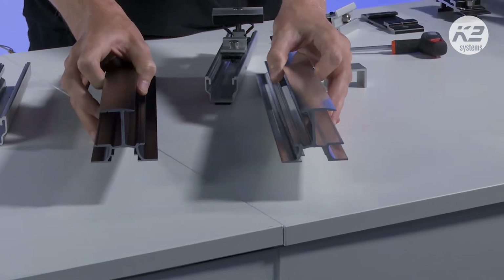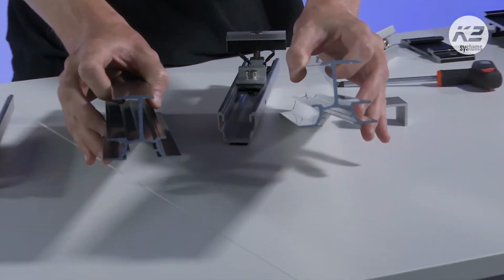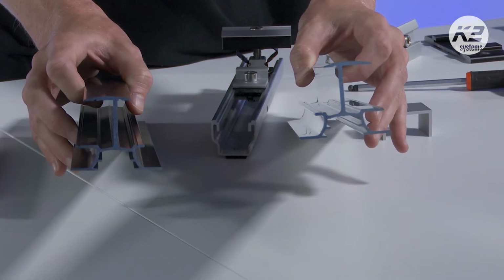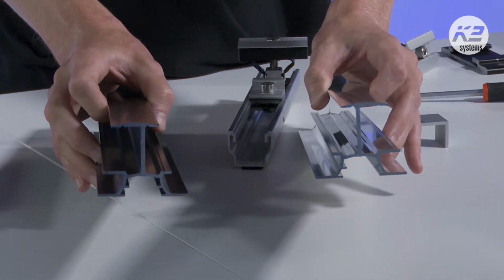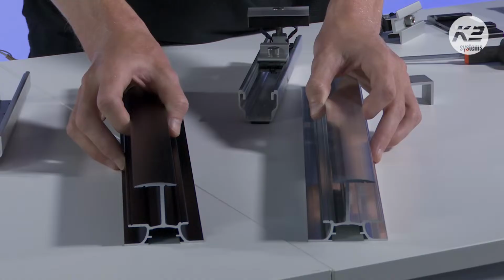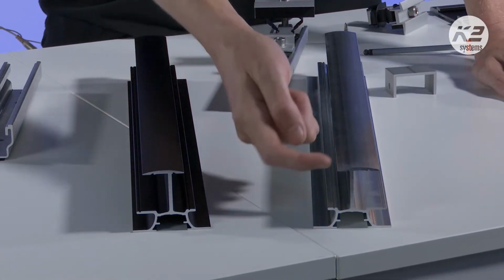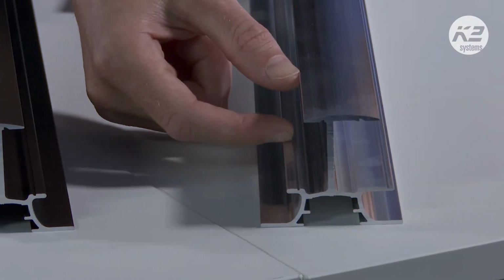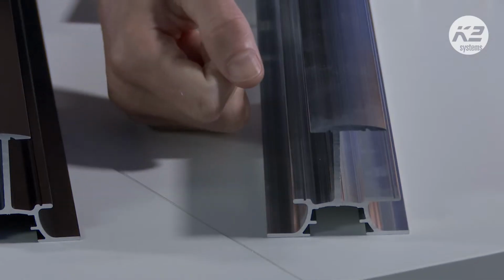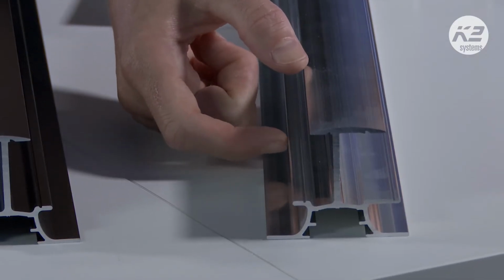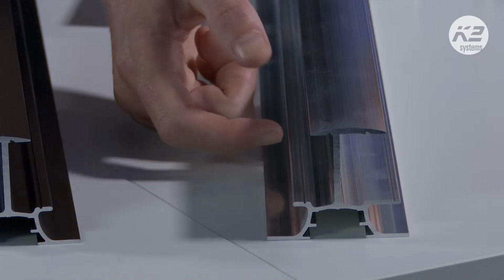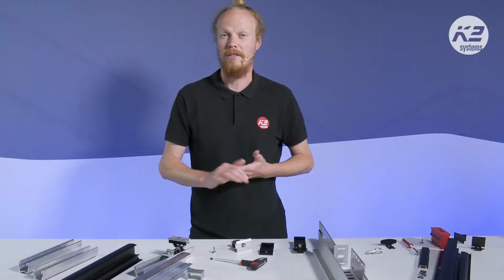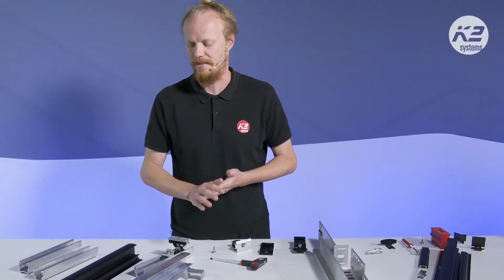The modules actually sit in the channels that you see here, and they can be sat in portrait or in landscape. It doesn't really matter, it's up to you. Obviously, one key point is that this thickness, where we're going to hold the module, is a certain width. We have one option that's 30 millimeters and one option that is 40 millimeters. So if the panels are anything other than 30 or 40 millimeters, the solution isn't going to be suitable. But with the majority of panels today, you see around 30 millimeters, so in the majority of cases it is suitable.